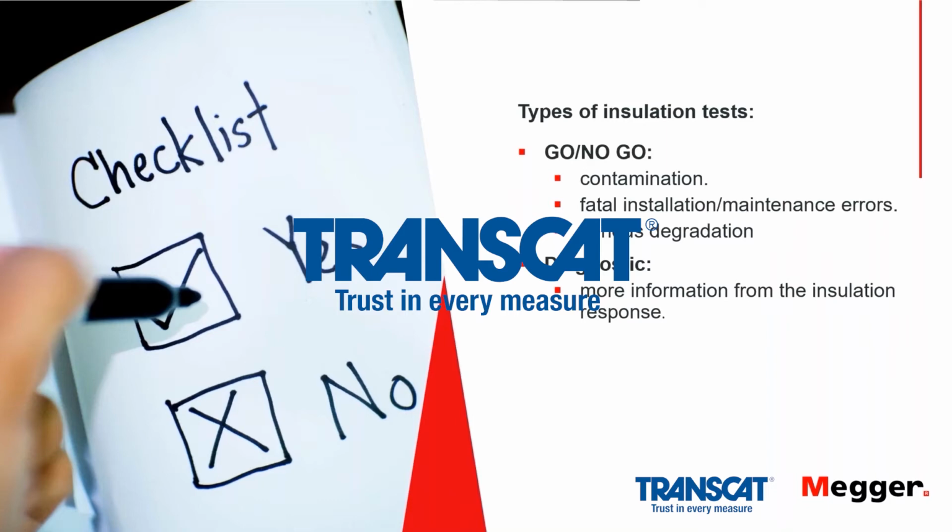The common unit of measurement, of course, is the megohm, 1,000,000 ohms, and that's what is most commonly used in insulation megohm readings. But 1,000 megohms goes into the gigohm range, and then 1,000 gigohms is up into the teraohm range. So you can see that's absolutely enormous, far beyond the measurement ranges of most types of electrical testers.